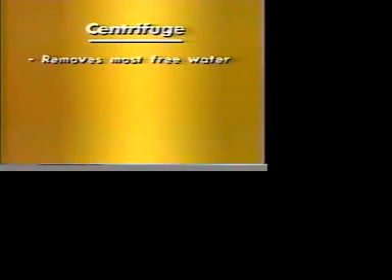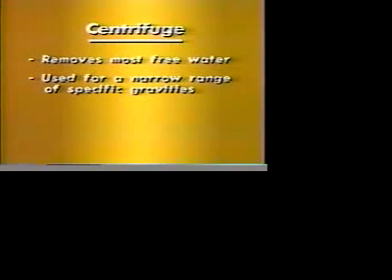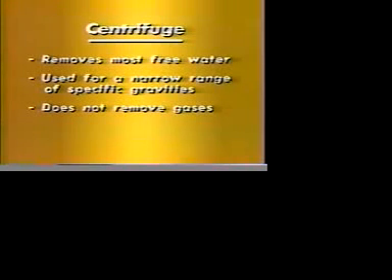Centrifuge methods are prevalent very frequently in the industry. Centrifuges remove all except trace amounts of free water. 20 weight parts per million is normally still left in the oil as free water. They are suitable for a relatively narrow range of specific gravity. They will not remove entrained gases. They are good for the purpose of removing very large slugs of water, and this is their primary function.